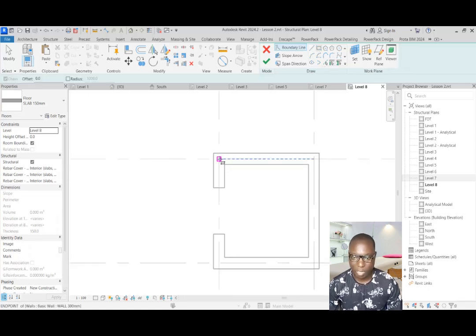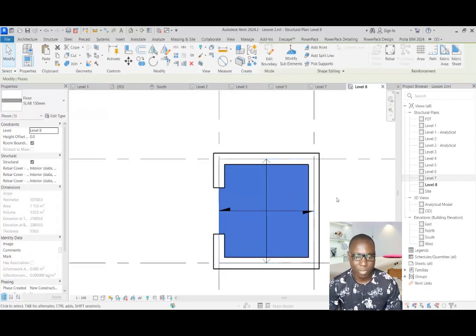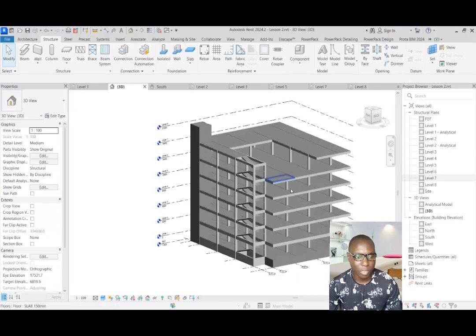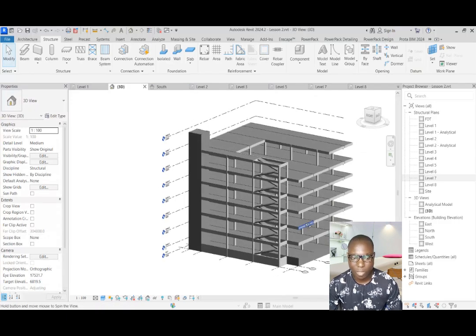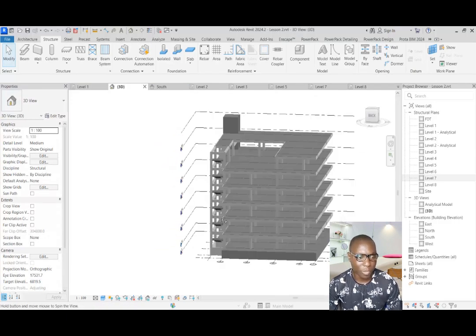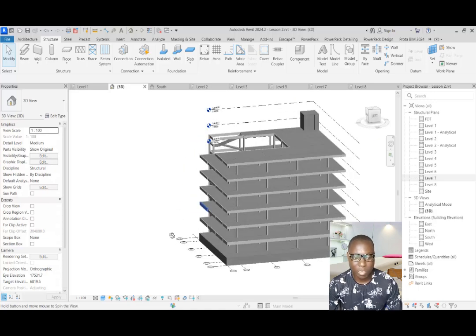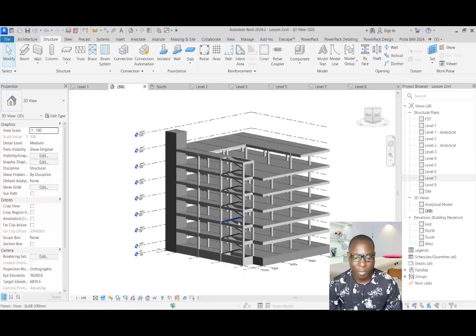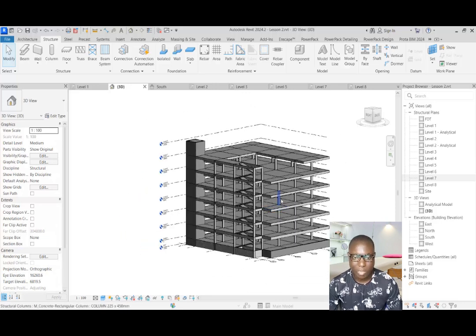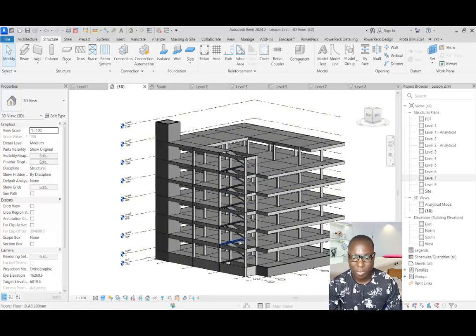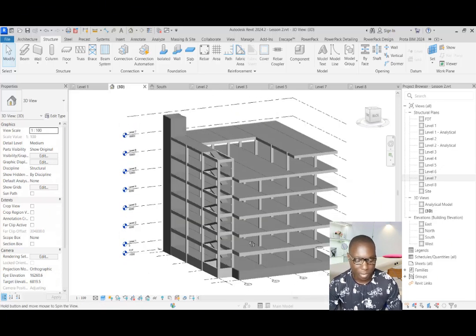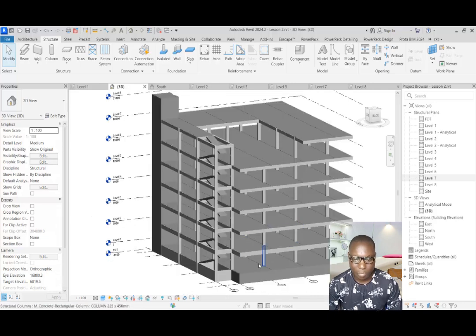Navigate to the level 8. You have the lift well. We need to also cover it with reinforced concrete slab. We get back to structural tab, selecting this provision, structural slab. We used 150 slab thickness, these options. All right, and then we pick from that point rectangle. So we placed it just like this and click on the finished to have it placed. Okay, if we get back to 3D, this is what we are now having. So with this, we are done with this modeling.